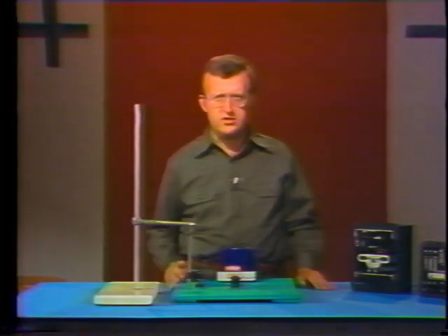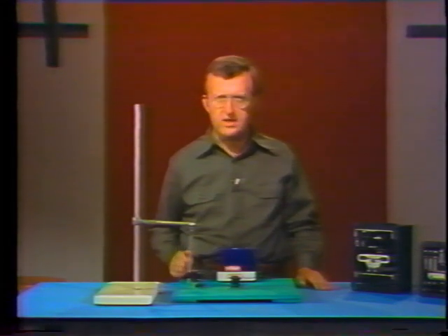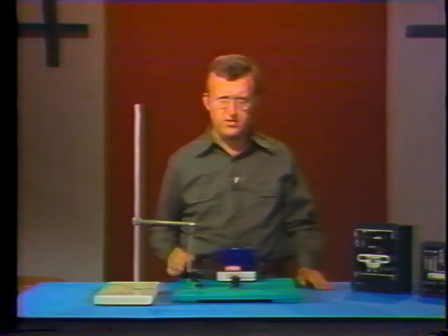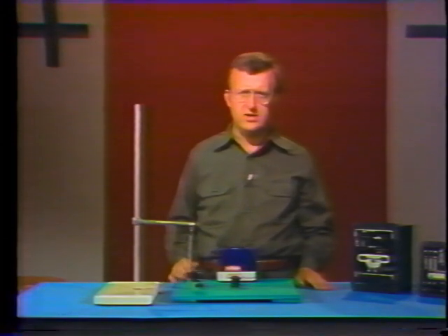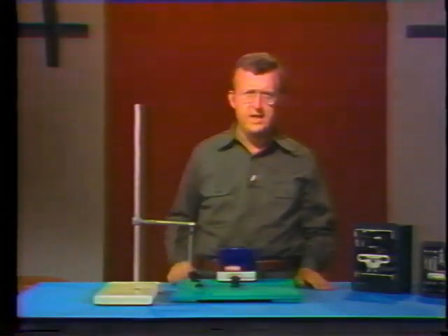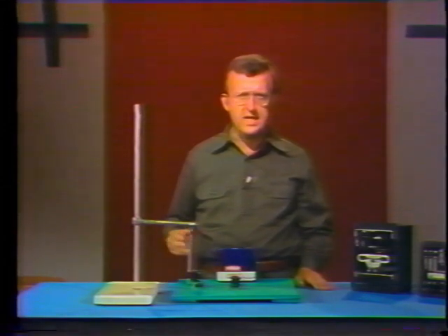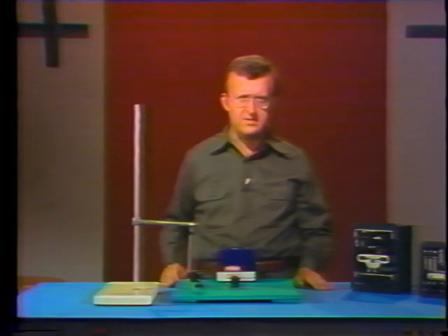Other types of relays, called control relays, are used to operate other relays. They're often used in automatic control circuits, in which a small electrical signal sets off a chain reaction of successively acting relays to perform various functions. Control relays are also used in interlocking or interposing situations. For example, we might use control relays to make sure that a pump cannot be started until all its valves are in the proper positions. By interlocking control relays, we can make sure that a reversible motor cannot be energized to run in forward and reverse at the same time.